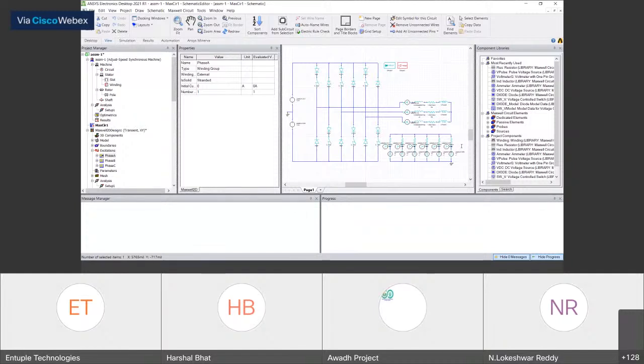Generally, when we do an insulation study, we are not really looking at the final breakdown. We are looking at avoiding breakdown, and for that, the value of stress in the insulation is generally sufficient, because that tells us how long the insulation will sustain that electric stress. So we can work on reducing the stress on the object and avoid a potential breakdown in that manner. Generally speaking, it's not required for insulation studies.